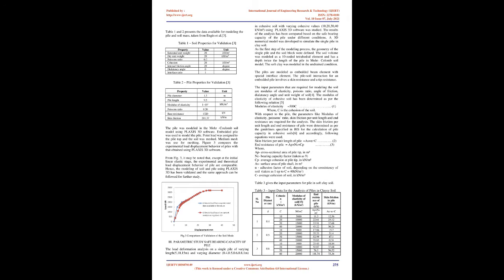In soft soil, the pile makes use of the strength of the soil by skin resistance along the shaft of the pile. Here the load transfer of piles is the sum of the toe resistance and skin resistance in soft soils. Methods adopted to find the bearing capacity of piles are static formula, dynamic formula, and field load tests. The static formula method relates soil shear strength to the skin friction along the pile shaft and to end bearing below the pile point. Both the skin friction and the end bearing resistance are used to calculate the bearing capacity of piles of any dimension in cohesive and cohesionless soils too.